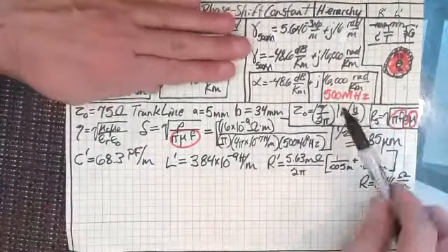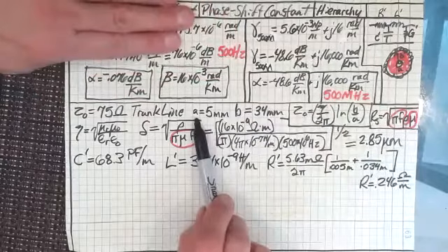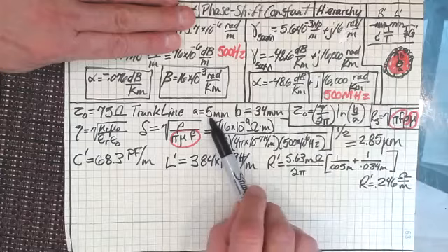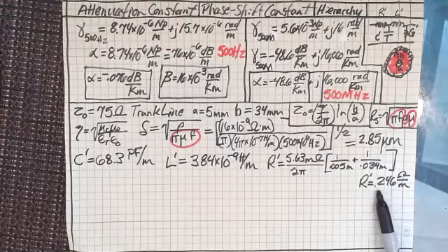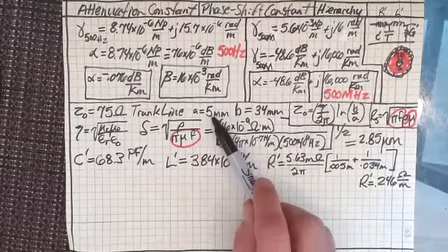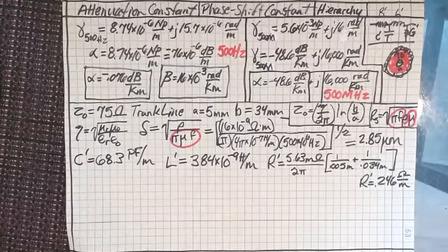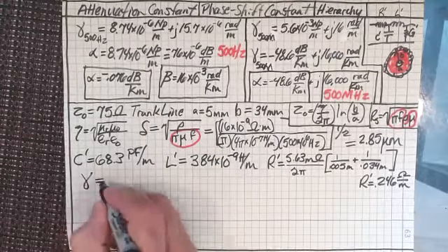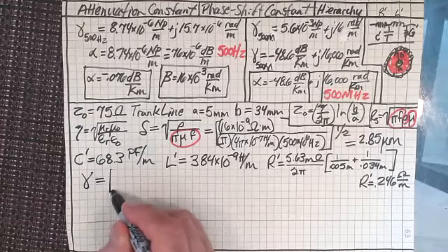But here, what we're doing is we're comparing both at 500 megahertz, keeping the frequency the same, but now changing the inner diameter from 1 millimeter to 5 millimeters. And you can see that that reduced this by about 4, a factor of 4. So increasing by 5, decreases by 4. Now how does that work out for the propagation constant?